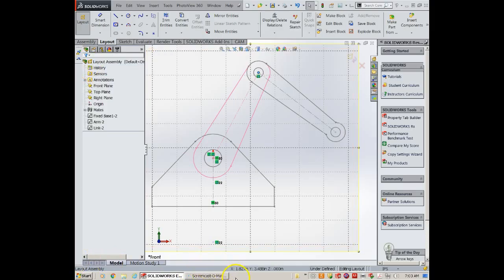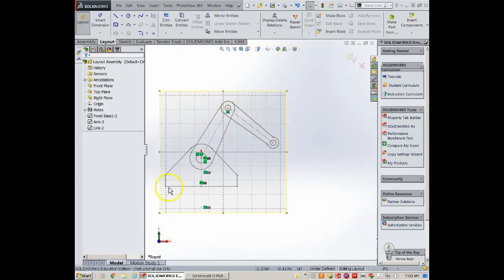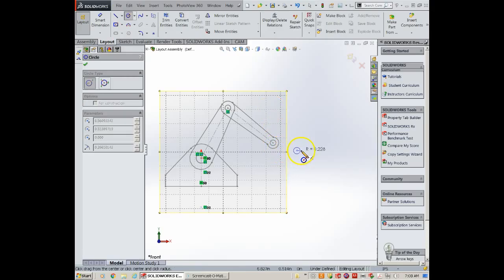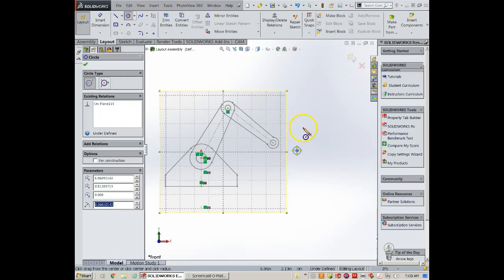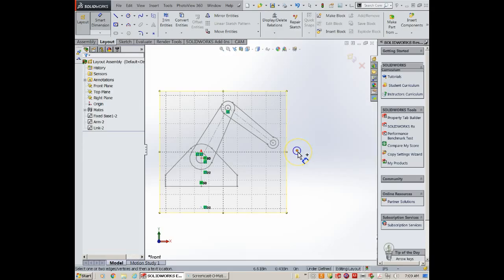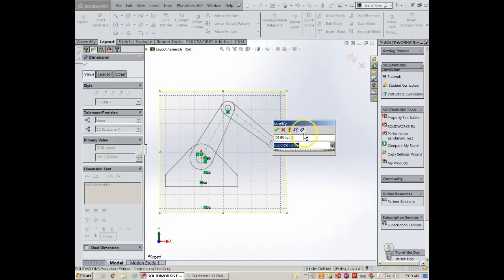We're going to create a new sketch to add to this selection of blocks. You can see the sketch tools are available in the layout tab. So we're going to draw the figure shown on the top of 12-4. So let's start with the circle, and the circle has a diameter of 0.710.